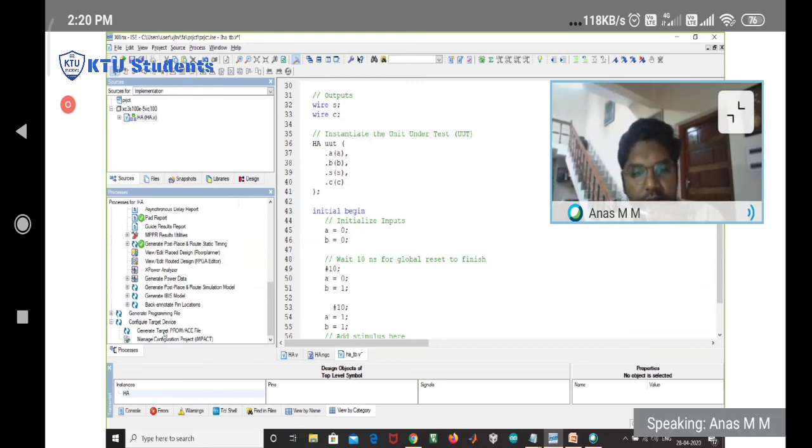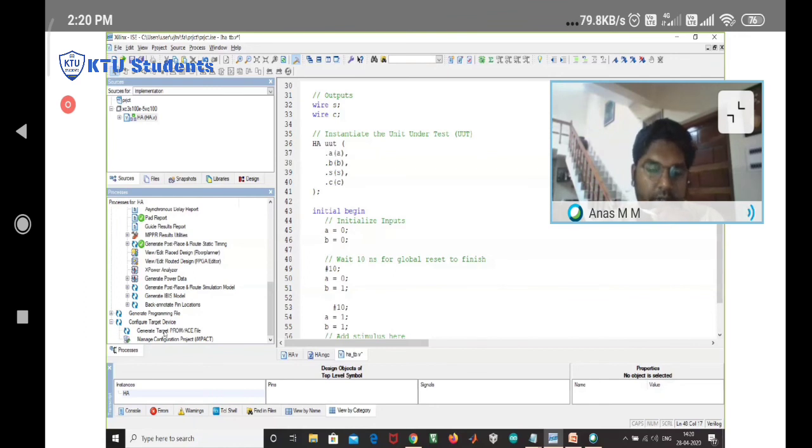Once you burn the program to the hardware, depending on the lookup table we mentioned, we can place it there. Two lookup tables will be used for the hardware, and we will get the half adder circuit in FPGA. And like one of you asked about CPU, we can create a 4-bit, 8-bit, 16-bit, or 32-bit processor. Once we express the processor hardware or architecture in HDL, we can burn that hardware to the FPGA. Then the FPGA will act as a processor.